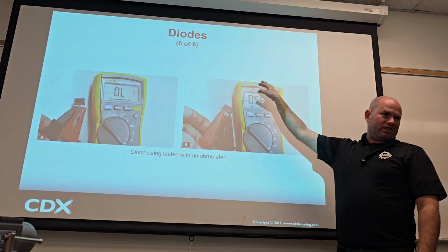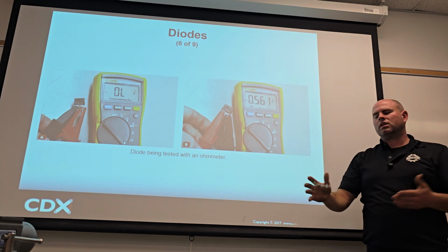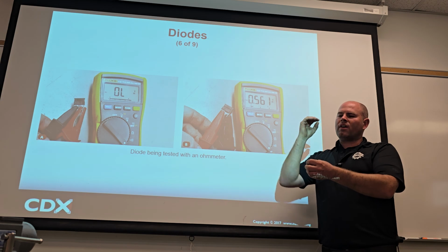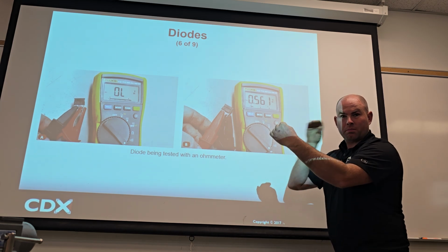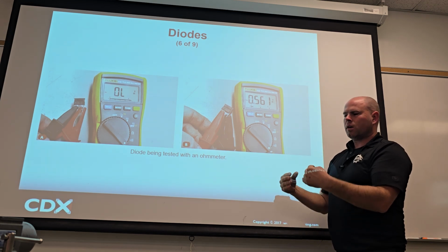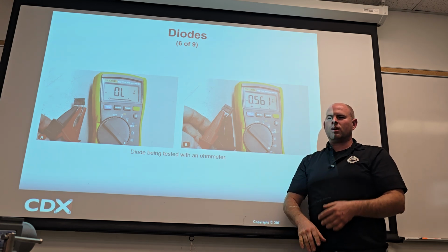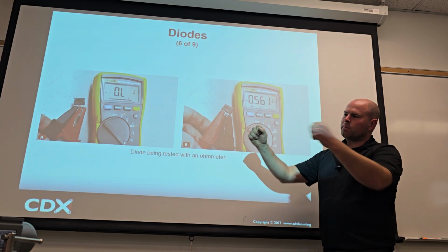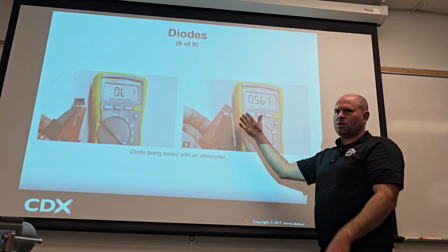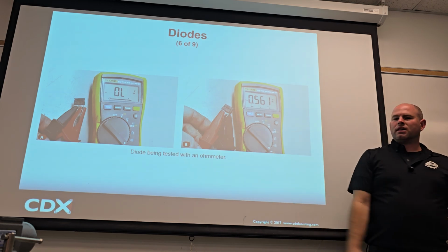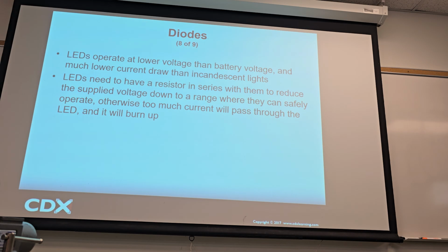And right here, I don't really have any specs. As we get into thermistors, they're really good about giving you specs. We'll get a measurement and reference it to service info, and the service info will tell us that at this temperature, it should be this much resistance. And you're like, oh, okay, cool. But you have to be in there all the time. That's why working on cars isn't what it used to be, where you look at it, take it apart, and put it together. You have to be in the service manual following the steps, or you're going to be off the path and misdiagnose it. And you won't even know why you misdiagnosed it because you never had the specs.